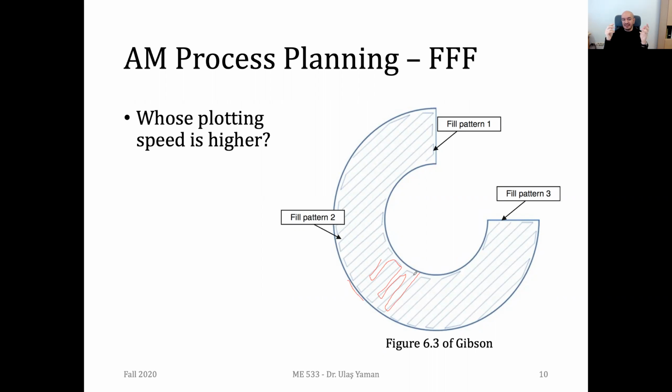If the quality is low inside your part, no problem, but the quality of printing should be as high as possible at the outer shells, since that will be the regions you're going to see after the part is printed. And you can obtain higher quality with low speeds, so that you can make sure that plastic is printed properly.